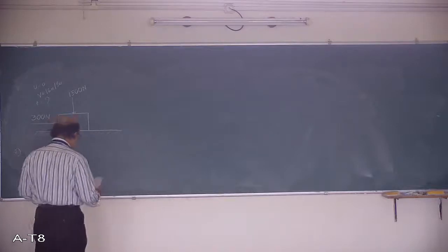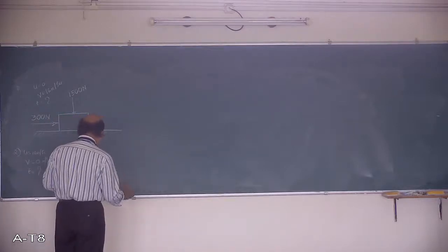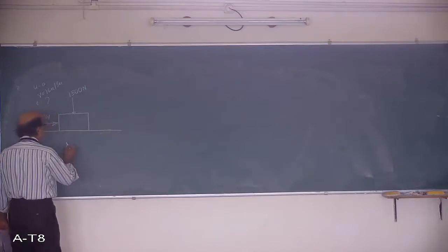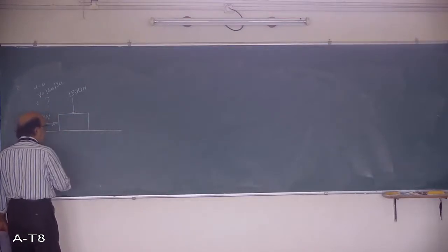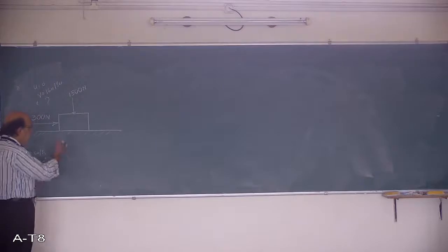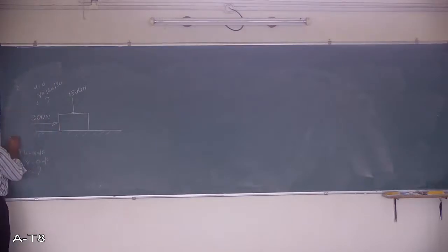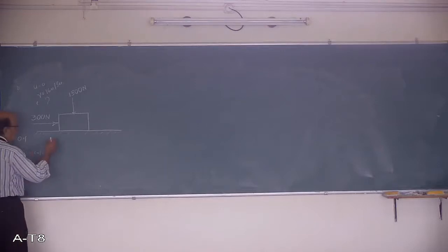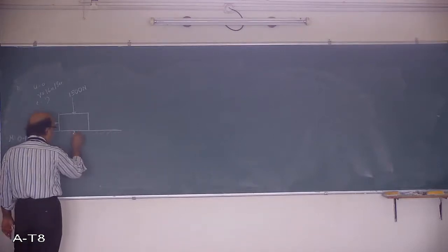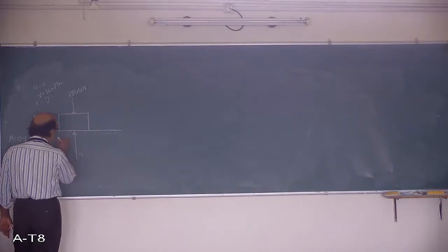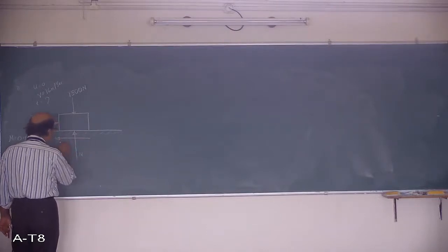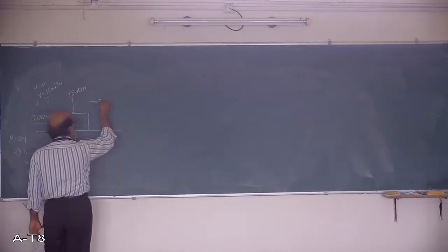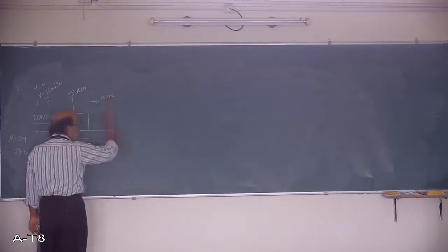The simple thing is that you can directly apply the equations. Only, initially you have to work out, as the block is moving in this direction, what other forces act. There is a frictional contact between these two, and mu is equal to 0.1 is given in the problem. The normal reaction acts as it is on the plane floor, and the frictional force always acts opposite to the motion, as the block moves towards the right side.